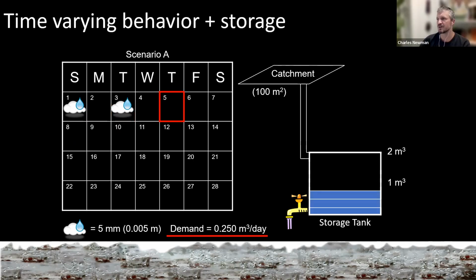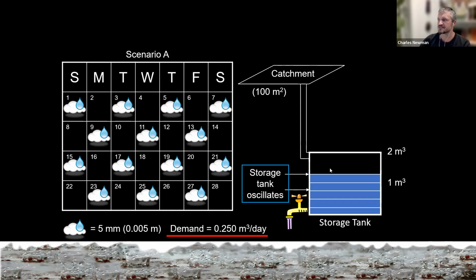And we cycle through this sequence, and you can see that the amount of water in the tank is oscillating roughly within the center of the tank. That means that all of the water over the course of the month is captured. I would argue maybe this water tank is a little bit too big, but it is, for all arguments, appropriately sized. And again, 100% of the water is captured for consumption.